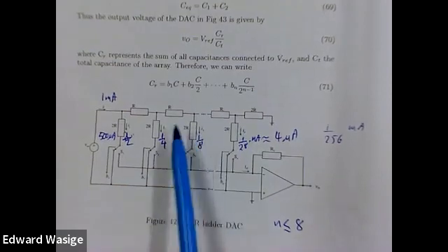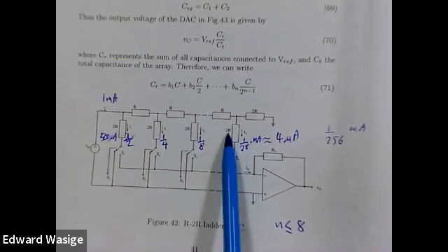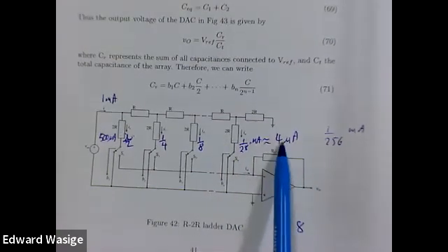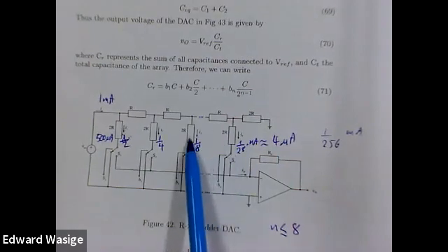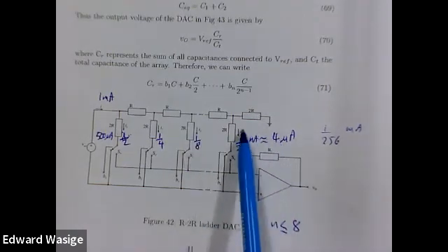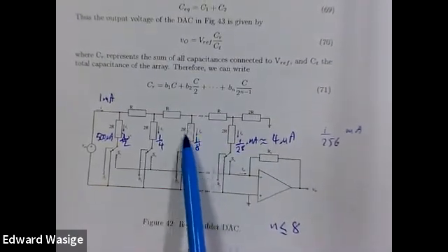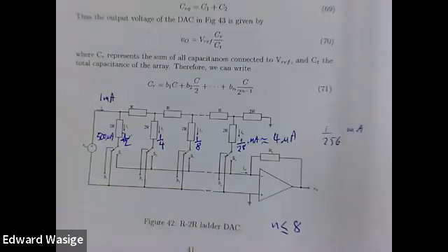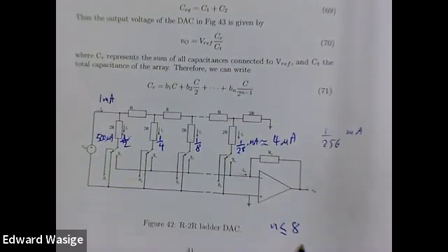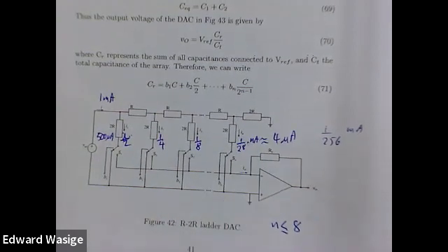So in the manufacturing of our circuit, if we have an error, if this resistor is 2.5R instead of 2R, then this can change, and if it's 1.5R instead of 2R, the current flowing through here might be the same order as the one flowing through bit 7. And so you don't have accuracy. The circuit is not very accurate. So that's why we have up to 8 bits. We can design and manufacture this circuit accurately. Beyond that, we start to struggle.